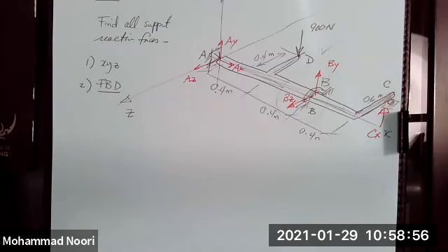Whichever direction you try to push a tree in whatever direction, you cannot bend it at the base. That means at the base, you do have a moment that is resisting. Also, you cannot move the base in any direction. So that base also represents three forces in every single direction. So that's how you visualize the unknown forces. Did that answer your question?